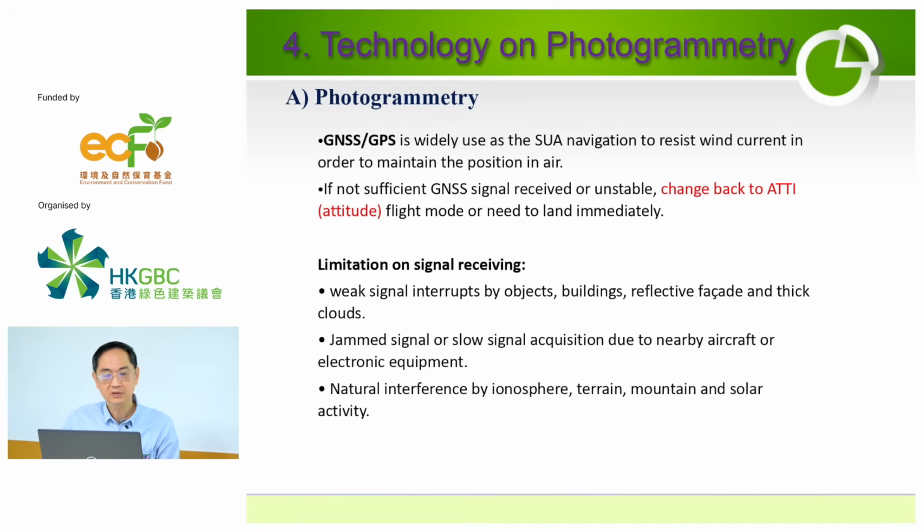But due to this factor, we need to limit our flight because there are signal receiving problems or weak signals interrupted by objects, by buildings, by the reflective facade. Okay, although the CIC is going to give us the guideline on the cleaning of the facade, there is a problem with the reflective curtain wall facade because it is glassy.